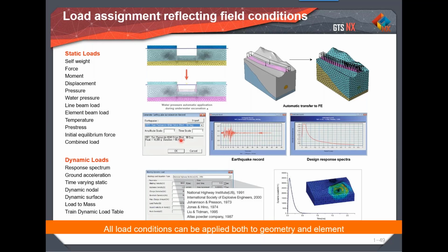Since we have the database of various earthquakes, you can even take the response spectrum of these earthquakes and get the analysis done. Or else you can simply create the design spectrum according to various codes, and you can use that for the response spectrum analysis as well. So that's up to the user.